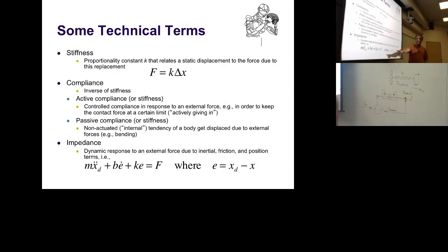What you get is a huge amount of impedance proportional to the mass. So the thing is heavy like hell. You get some viscous friction from the water, but you have no stiffness because there's no stiffness in the water, which is very relevant. So it's a typical example where suddenly the inertia and the friction are very noticeable. Good. So many people then in the end say, what you really want to do is impedance control. And what this video was showing you, it was a dynamic movement all the time. It was doing impedance control. It was trying to make the robot behave like another physical system. And that's really what it boils down to.